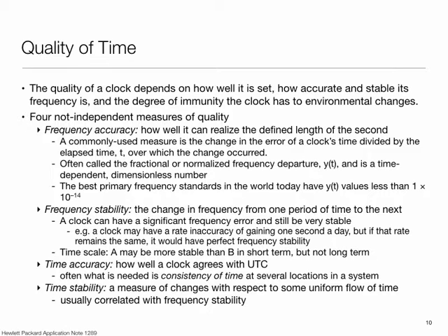If at some point in the past I had a known offset, and I also know that the oscillator has a fixed frequency, but that frequency is wrong, then I can learn that frequency offset and use it in a linear expression from that point on. The problem is that frequency itself is highly unstable because it depends upon various environmental factors, and that makes the whole process challenging.